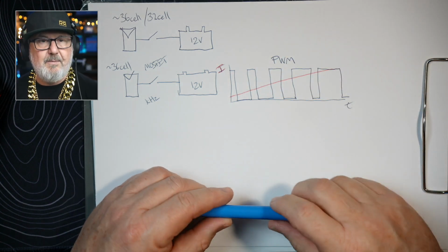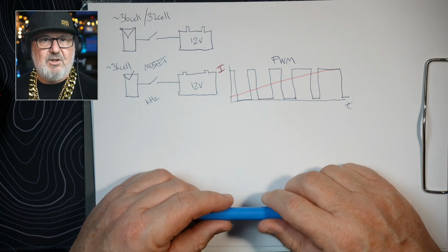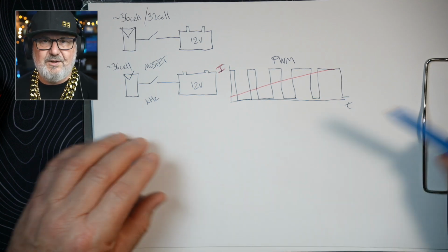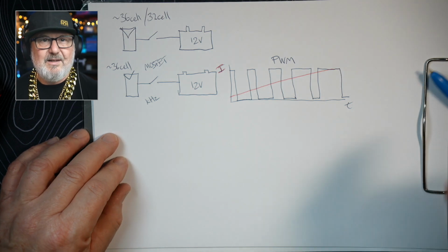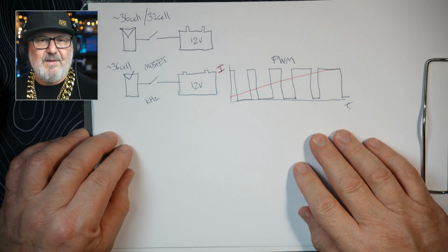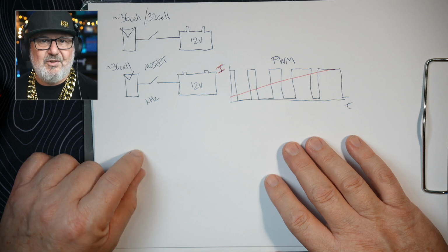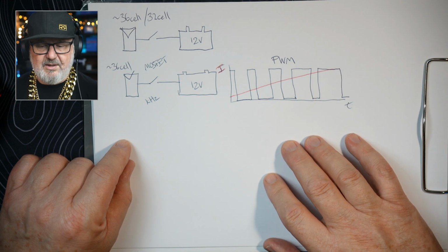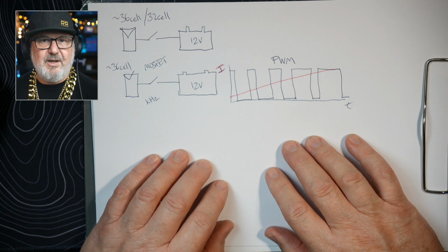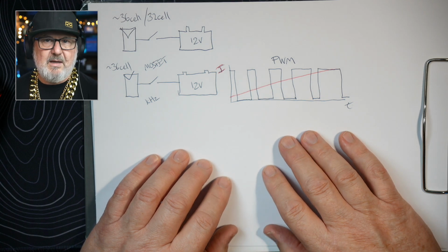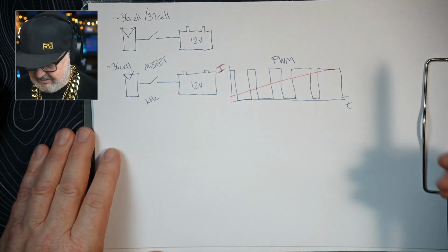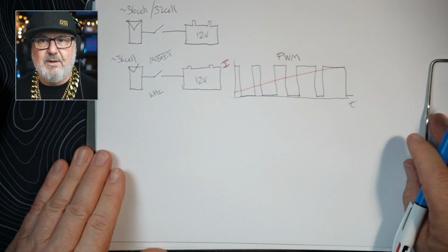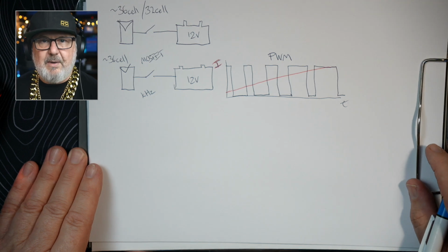In fact, PWM is extremely cheap and simple. If you go to, say, boating, fishing, camping, and buy yourself a little so-called regulator, it will be about the size of a matchbox and goes on the back of the solar panel, and it's doing exactly this. It's ensuring that the battery is not being overcharged. So it's very cheap to make, very simple. But the problem is that you've now locked the solar panel to the battery voltage.